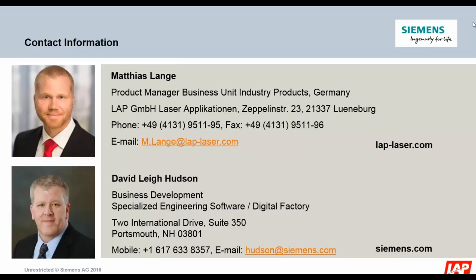I guess that's a question for me. So as part of the flat pattern being generated, one of the things that FiberSim does is allow you to assess the manufacturing producibility based on three things: the part shape itself, the material and material form that you're using, and the manufacturing process that you expect to use, whether that's a manual layup process or something different.